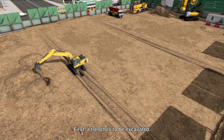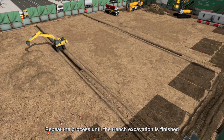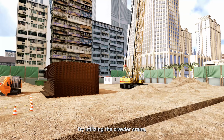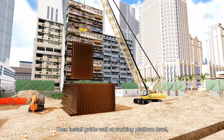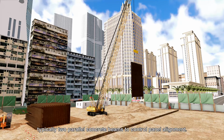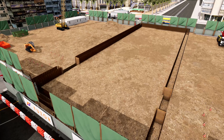First, a trench is to be excavated. Repeat the process until the trench excavation is finished for the panel excavation later on. By utilizing the crawler crane, grab the steel and insert it into the trench for the guide wall. Then install the guide wall at working platform level, typically two parallel concrete beams to control panel alignment.